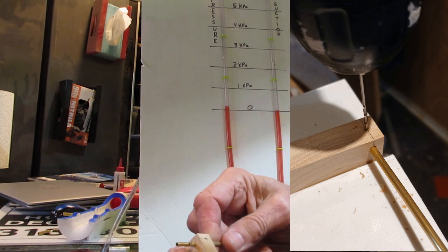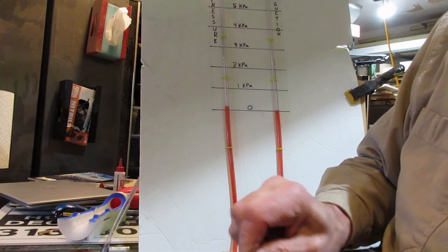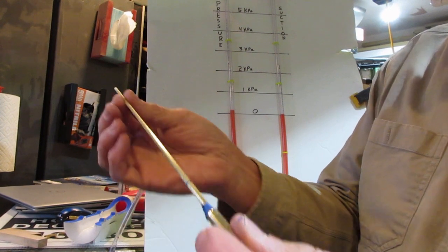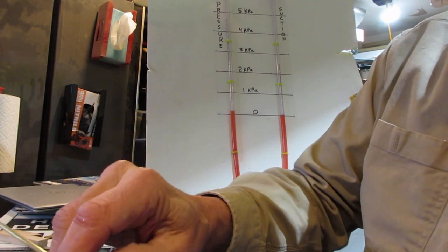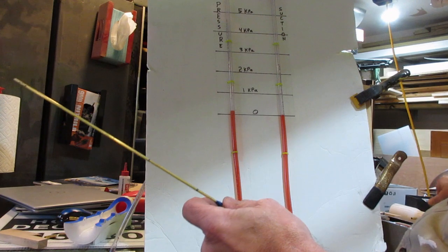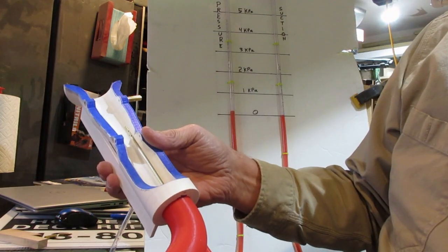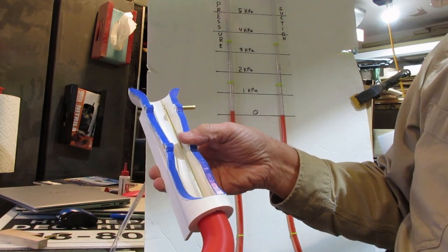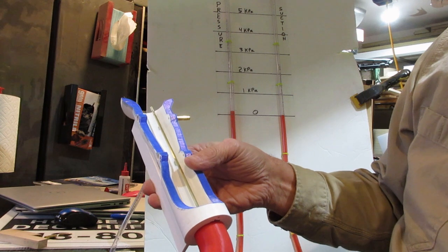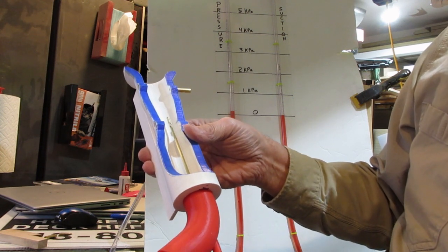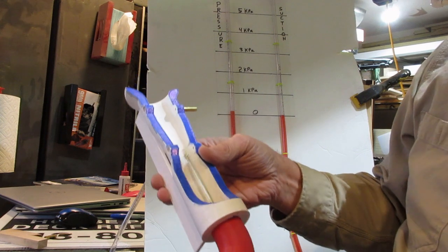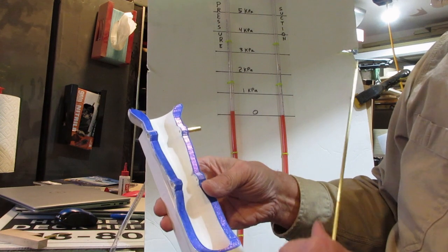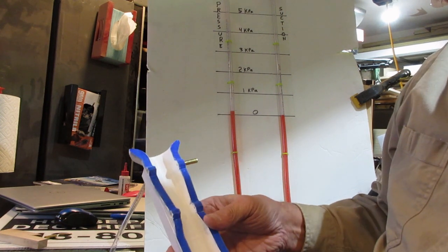It's not perfectly square. Okay, this is the static probe here. Again, the 1/8 inch tubing. I've got marks on it here and here that indicate when it's lined up about with this position or that position. But again, you can mark it in millimeters and get continuous data collection, of course, and graph that if you prefer, so you can calculate velocities or mass flows and see how they all compare at different points along that Venturi.